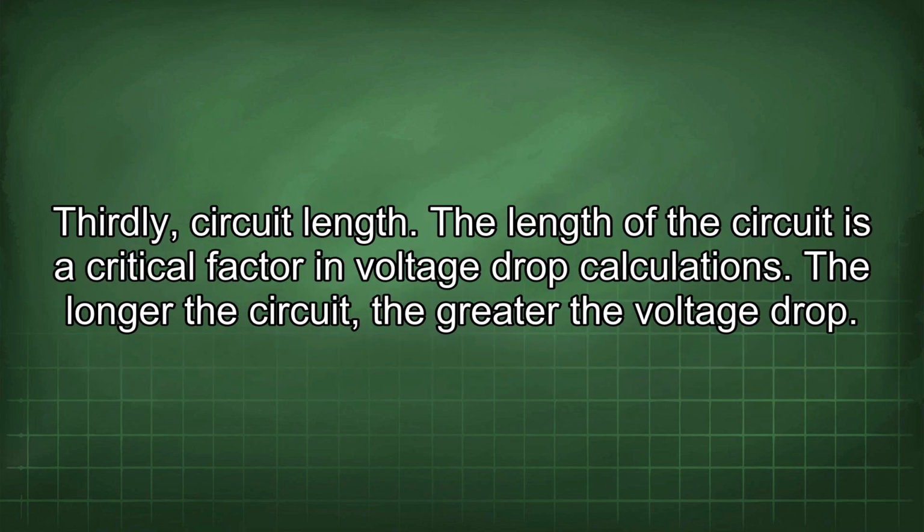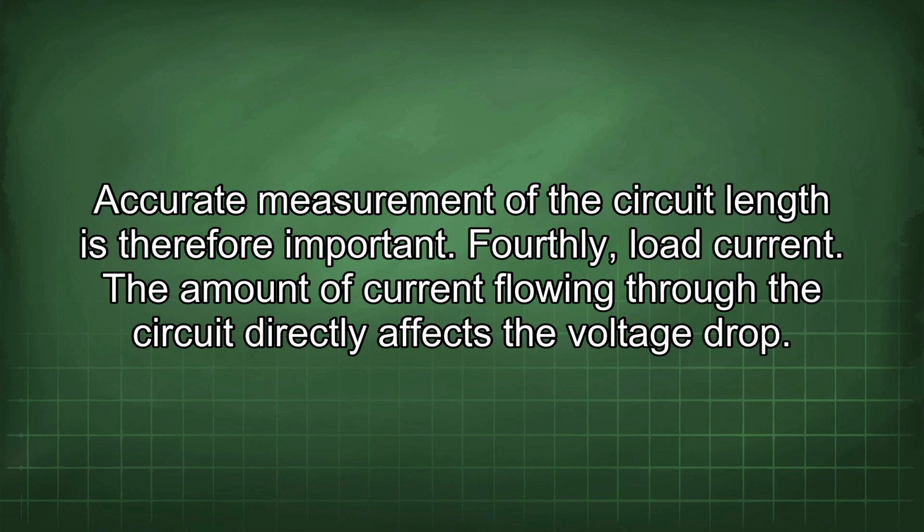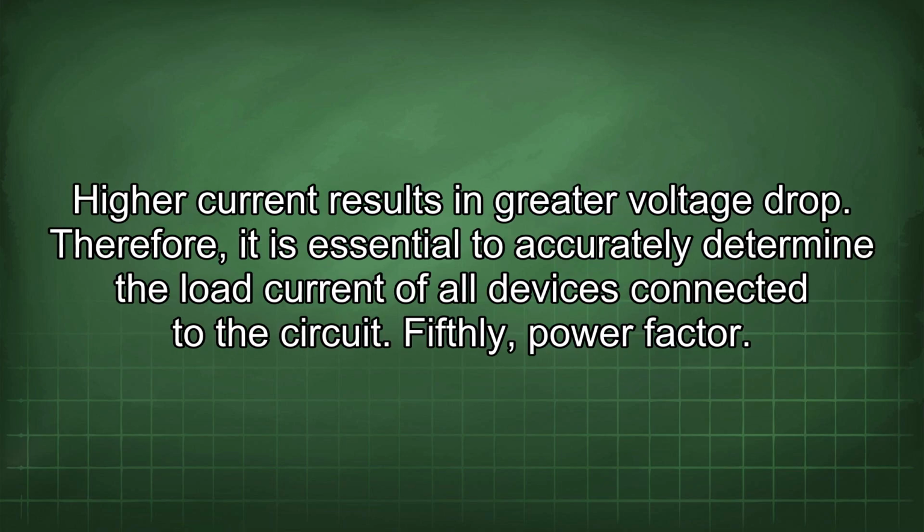Thirdly, circuit length. The length of the circuit is a critical factor in voltage drop calculations. The longer the circuit, the greater the voltage drop. Accurate measurement of the circuit length is therefore important. Fourthly, load current. The amount of current flowing through the circuit directly affects the voltage drop. Higher current results in greater voltage drop. Therefore, it is essential to accurately determine the load current of all devices connected to the circuit.